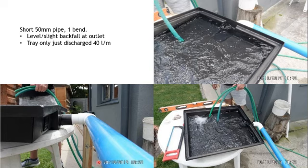So you can see that on the bottom left-hand picture here, this outlet immediately from the tray to this first bend has got a slight backfall, and you could probably call it level or slight backfall. The pipe itself has got a decent fall. So the tray has a beautiful fall on it, the pipe has a fall on it, but this 100 millimeter piece here has a slight backfall, or almost level. Now, just that little section of no fall caused this tray to back up like that. And you'll see why I say that in a minute. Yes, it's discharging. It's only just discharging at 40 liters a minute, but it's struggling.